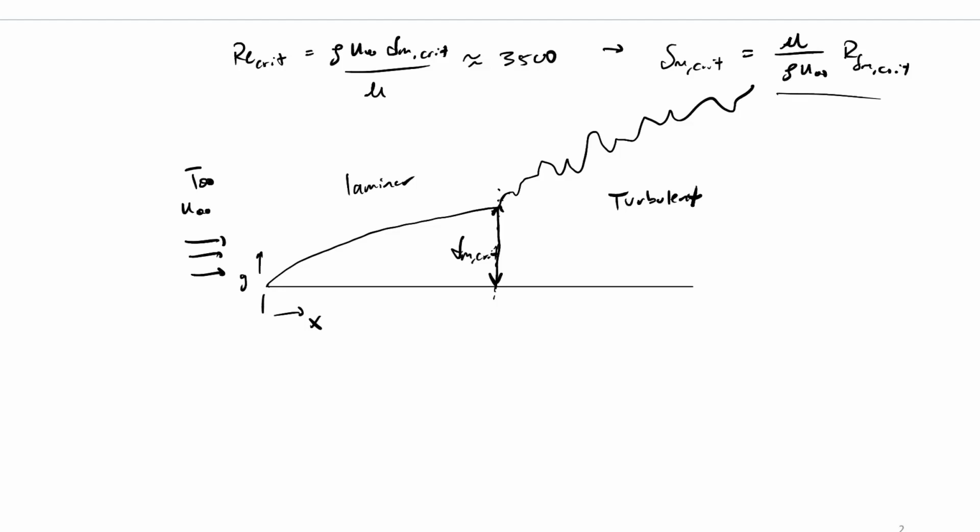This boundary layer, using our self-similar solution, delta M over x is equal to 4.916 divided by the square root of Reynolds in terms of x, right? That's the boundary layer thickness equation using the self-similar solution, which is an exact solution. We'll use this in combination with our other definition to solve for the relationship between the two.